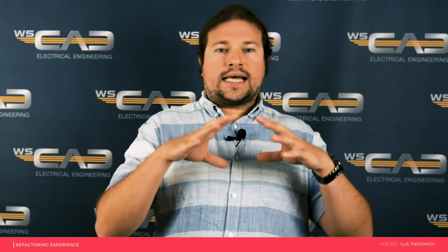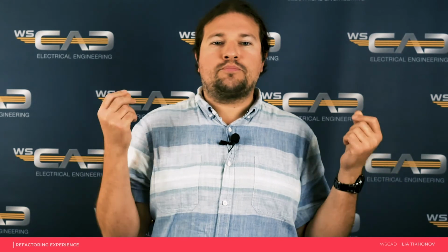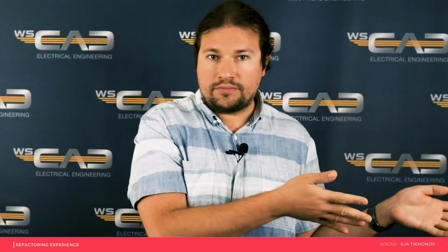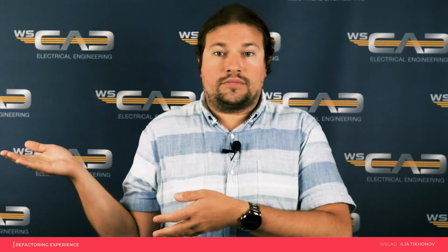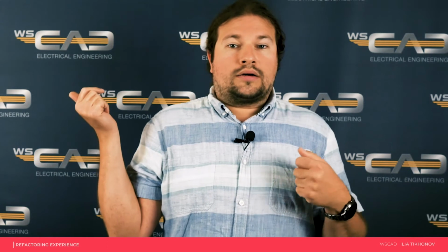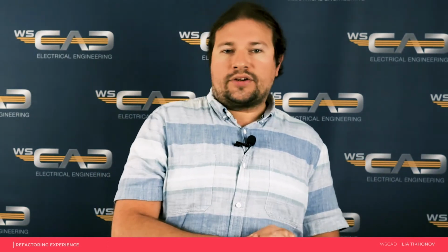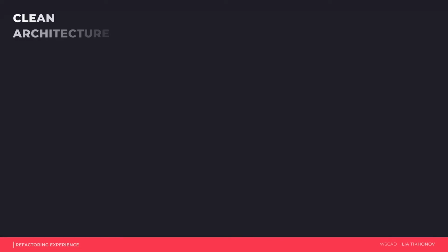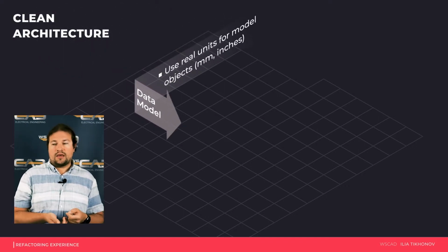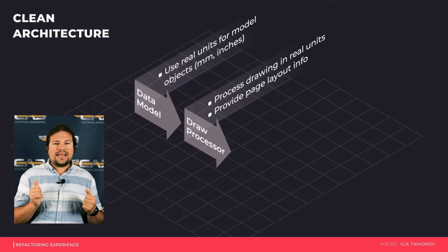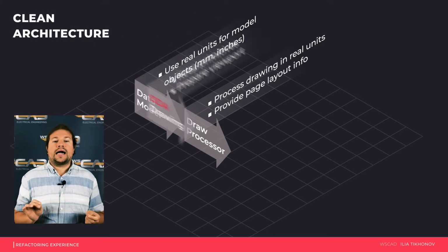When you are going to make such a big change in the core of your software, it's vital to understand the main difference between the current approach, a custom GDI drawer in our case, and a new one, ODA. So what were the main topics we learned? To get a clean architecture, forget about pixels. Use standard length units like millimeters or inches. Zooming and panning are actually parameters of a viewport. The rest of the application is not obliged to know about them.